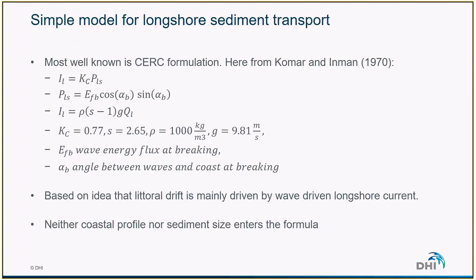It's important to note that in this formula, neither the coastal profile nor the sediment size enters the formula, for instance. But still, it's able to provide a good estimate of the longshore transport within an order of magnitude.